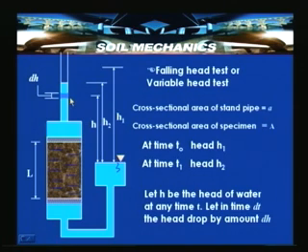By using this delineation, let us try to bring out a theoretical deduction so that we can determine an expression for the coefficient of permeability based on the falling head test. By dropping water from H1 to H2, a minute amount of water trickles into the soil. In the constant head test, we establish the water passing through the soil. The amount of water flowing into the soil is very less in the falling head or variable head tests.